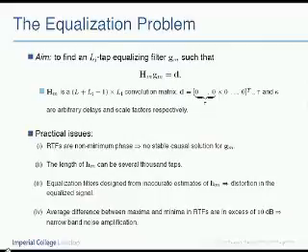Okay, so I'll look at the other side of the issue, which is the equalization. Let's assume that you have some kind of estimate of your room impulse response, H, and you want to design some equalizing filters so that when you convolve your impulse responses with the equalizer filters, you get an impulse, which can be a delayed or scaled version of a true impulse. And that's sort of the ideal equalization, I guess.